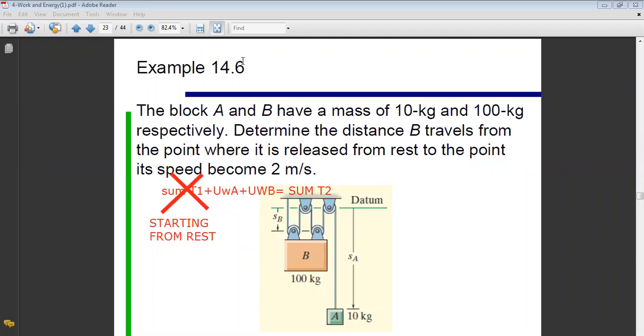So first, here we have considered coordinates downward as B down and as A down. For a downward coordinate, what is the expression of the work? If you remember, when we derived together the expression of work, we said it is minus W delta Y if Y is up, and plus W delta Y if Y is down.